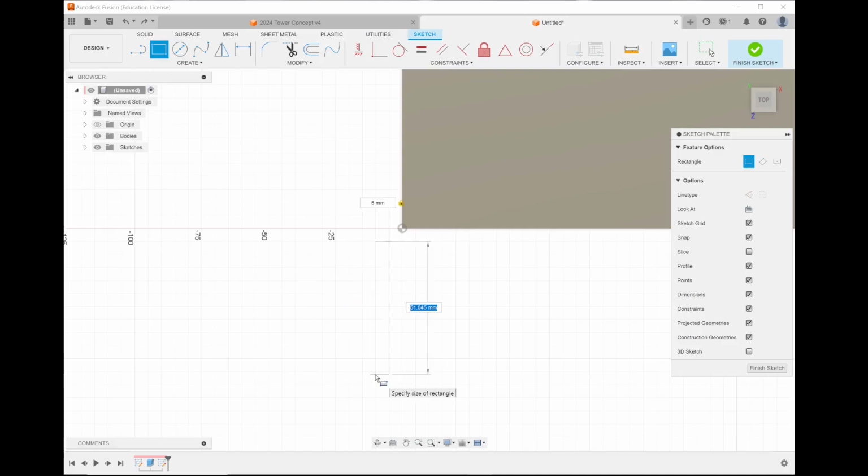That's very useful if you want to draw something at like an angle. So you put in the angle and then you can drag it however far you want because the angle will have the padlock in it if you write 60 degrees, for example. Once you type the number in the box and you press tab, then it will be padlocked, and it's not going to adjust. It's not going to rely on the mouse to adjust its location at that point.